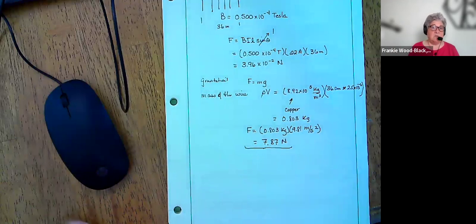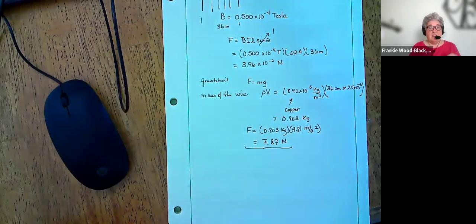But one set of cows was producing approximately 10 to 20% less milk than the other cows across the street. And the only apparent difference between these two dairy farms was that the cows that were producing less milk were under high voltage power lines. And so they thought it was the magnetic fields that were causing the reduction in milk production. Turns out that wasn't the case. There actually was a short in the milking barn associated with the farm that was underneath the power lines.